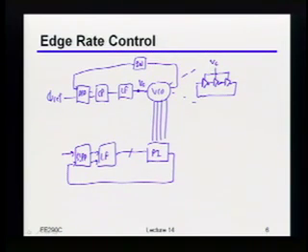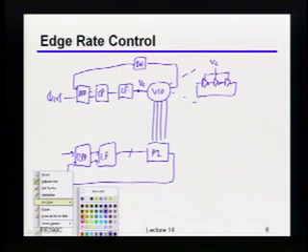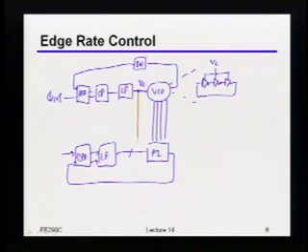Of course, I use that with the outputs. Okay? So what we're basically saying here is that if I just take that control voltage and use it to control the phase interpolator, or in particular to control the edge rates of the phase interpolator, then I can get this nice automatic tracking. Of course, you have some minor caveats, which we'll talk about in a second. Now I know that I've got this control voltage, and if I've done things the right way, I should also be controlling the edges inside of that phase interpolator.